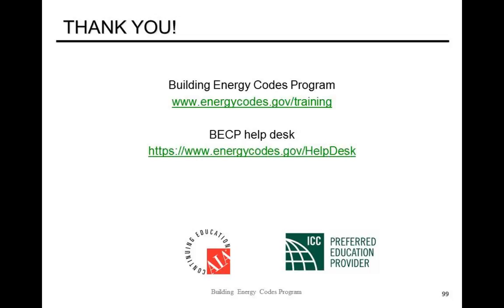Next question was, what is IER? The IER is actually a new metric that we developed for rooftops. It came about in 2010. It's basically a weighted average of the performance of the mechanical cooling of the equipment at 100%, 75, 50, and 25% load, with a scheduled ambient. It's kind of related to highway and city miles per gallon. It's a metric that'll allow you to compare units.